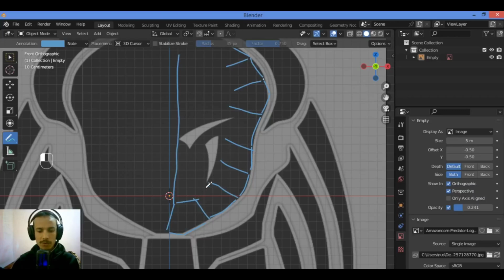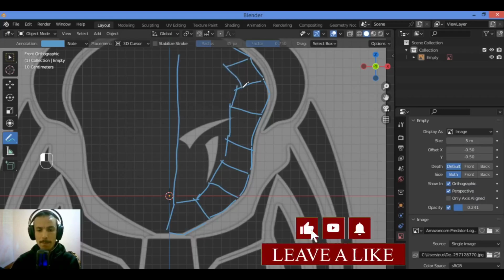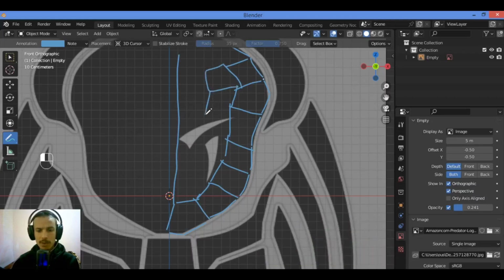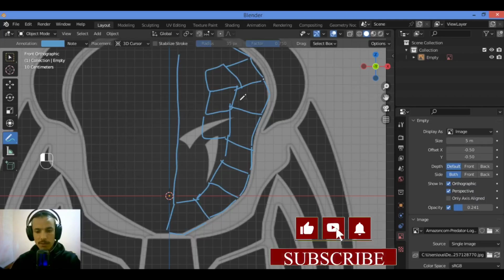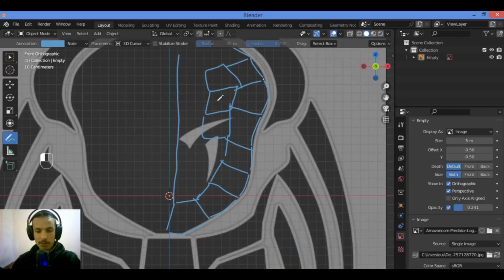In some cases you're going to get bad issues by creating quads, and that mesh should depend on all quad mesh, like this. By creating the right topology you can get better results when you render it, or when doing something else like adding materials and UV wrapping and all that stuff.